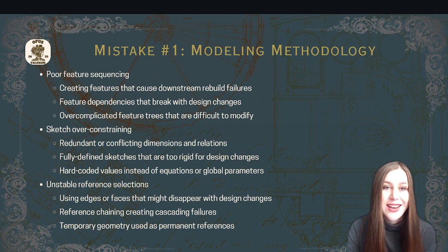It is important then to avoid unstable reference selections as well. With design changes, your reference faces or edges may disappear. You should avoid using temporary geometry as a permanent parameter. Further, reference chaining could result in cascading failures.